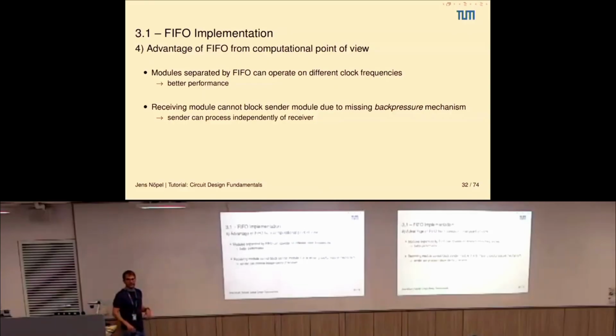And then it's a question, how do you dimension your FIFO? And this is what we have done before, thinking about what the different rates are, module A producing data and module B receiving. And then decide, okay, our FIFO must be, let's say, 450 packets large.